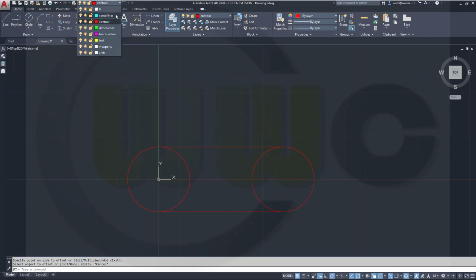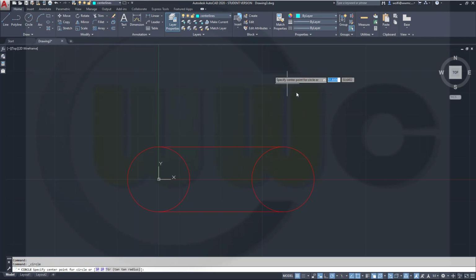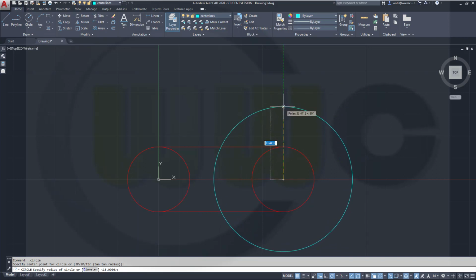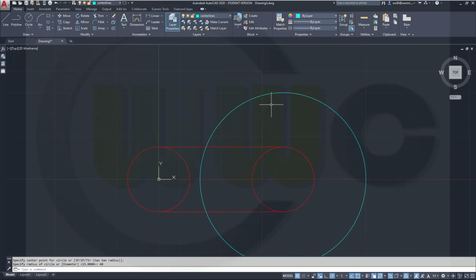Okay. Now for the last center point of the last circle, I need some sort of construction lines. So going for a circle which sits right on that center, and the radius would be 40. Then I need a line which starts at 20 millimeter distance of that point in that direction. So let's go here, go there, just draw a trace over to the left side and type 20. Then go straight up and select that point here.